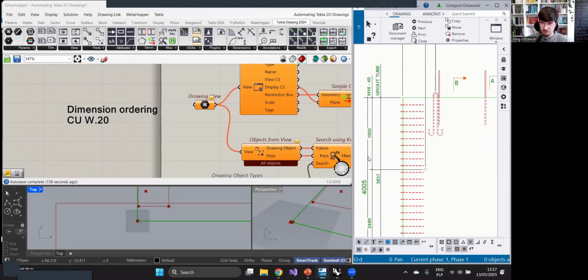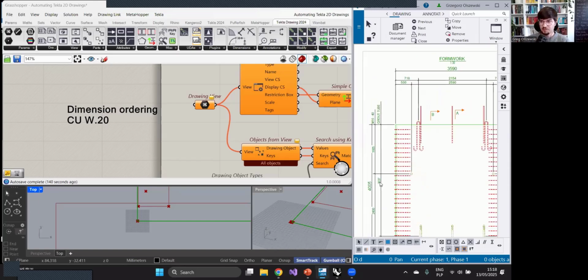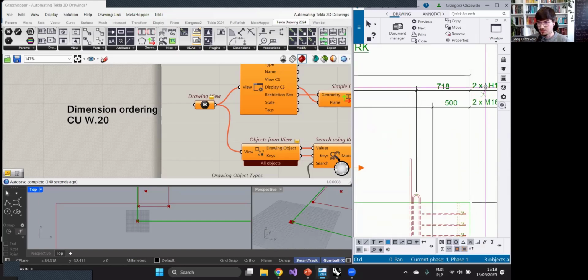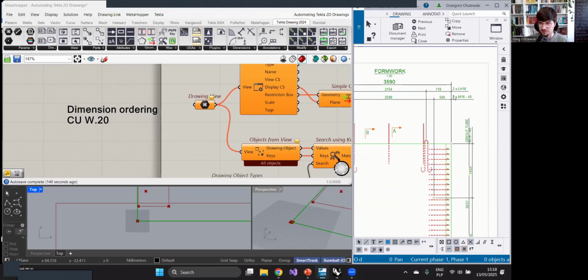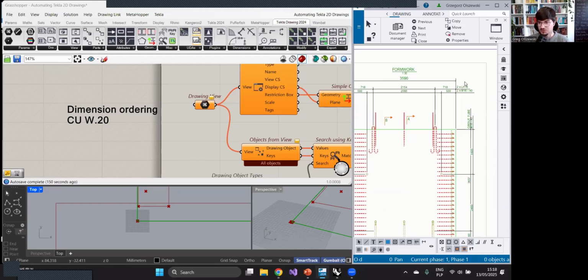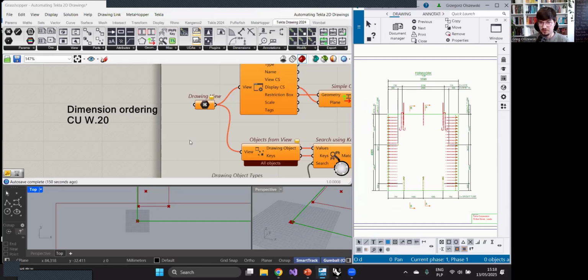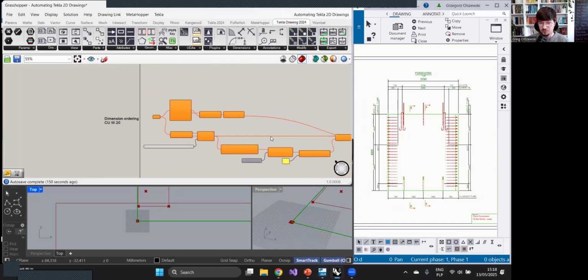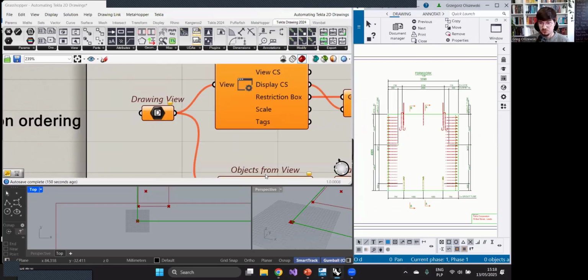This is the matter of the cloning, so getting the source drawing and then trying to apply the automatic Tekla behavior to the next one. From version to version, it gets a little better, but still very often you will see a situation like that, when you will have to just drag and drop those dimensions a little to get them positioned better without the overlapping. But with the drawing link, even with a smaller number of components, you are able to streamline that operation.